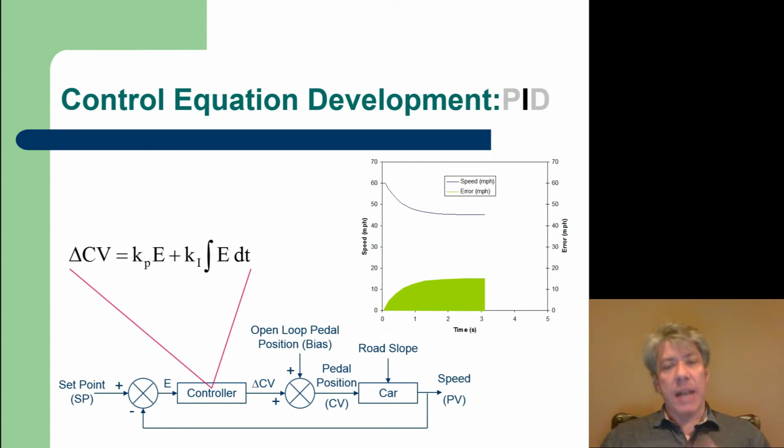The nice thing about this is that if we've increased our proportional term just as much as we feel comfortable, and yet we still have non-zero steady state error, in other words, our process variable is not at the set point because proportional control can't completely reject disturbances, then what will happen with the integral term is it'll start adding up the error and it will start asking to change the control variable, because look, it's an addition term, right?